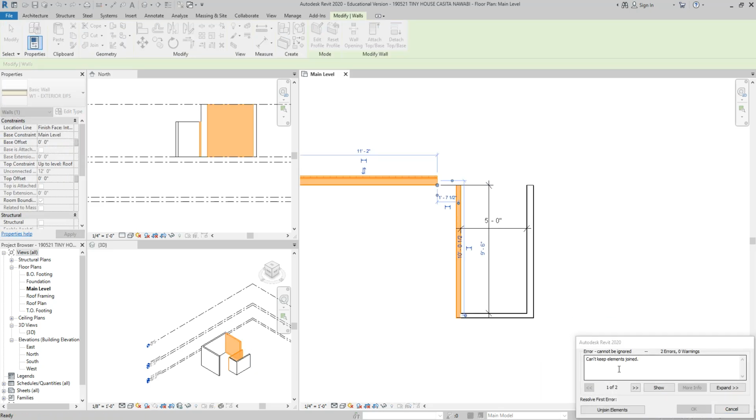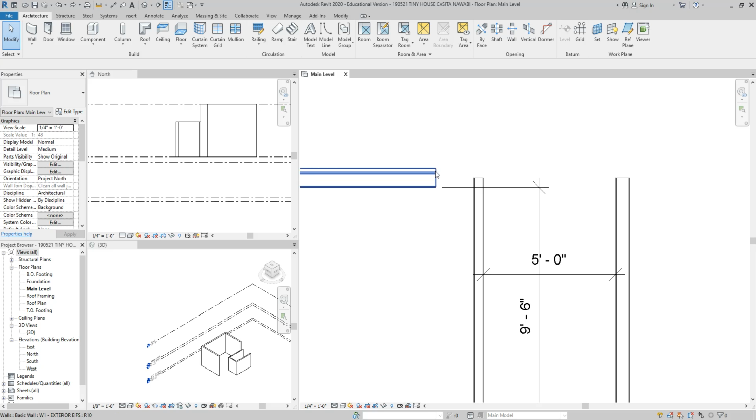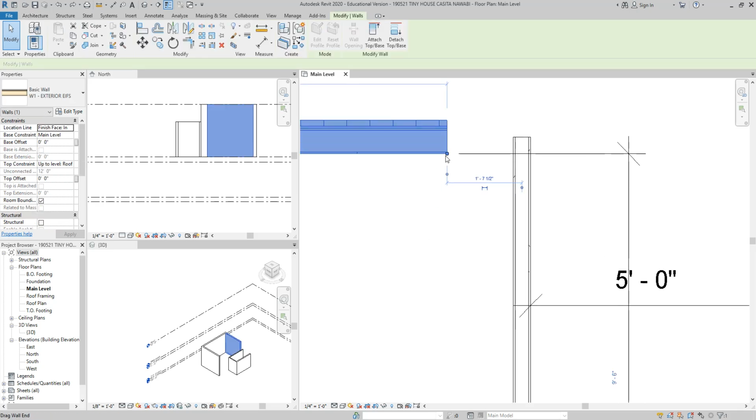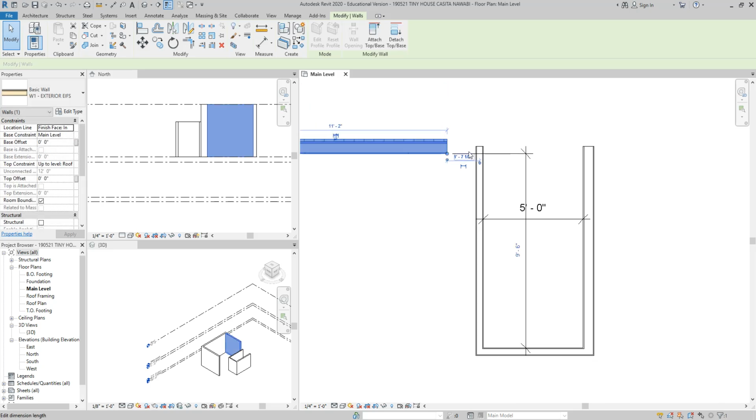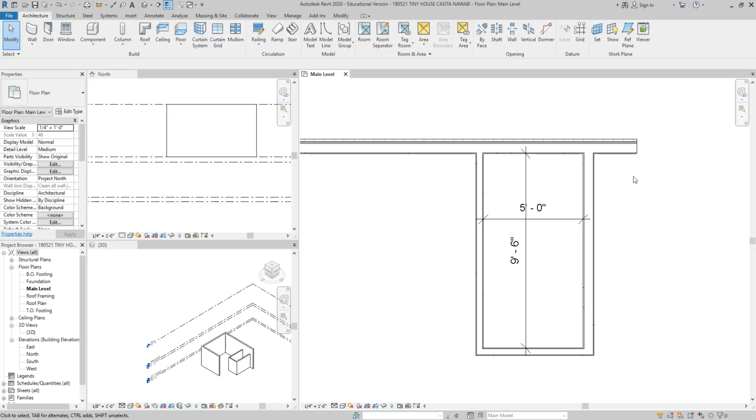So there's two ways of doing that. You can do the TR command and click on what you want to keep. So TR, and then essentially you can... So if I don't have that wall yet though, should I put that wall up before I... I can show you the second way, and then you don't have to do it the TR way. The other way is you click on a wall, and do you see this little blue dot that comes up, and when you hover over it, it says drag wall end? You can click on that and essentially drag it, you hold and click, wherever you need it to go.